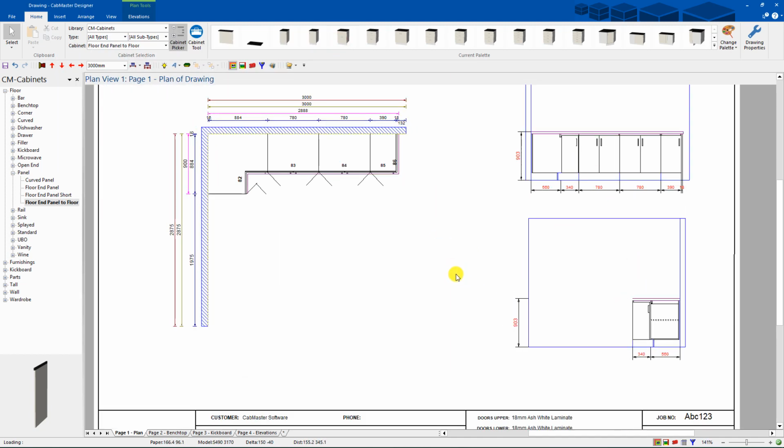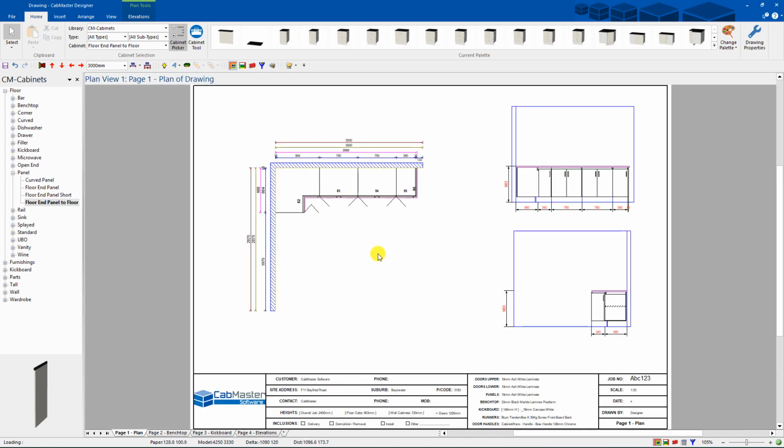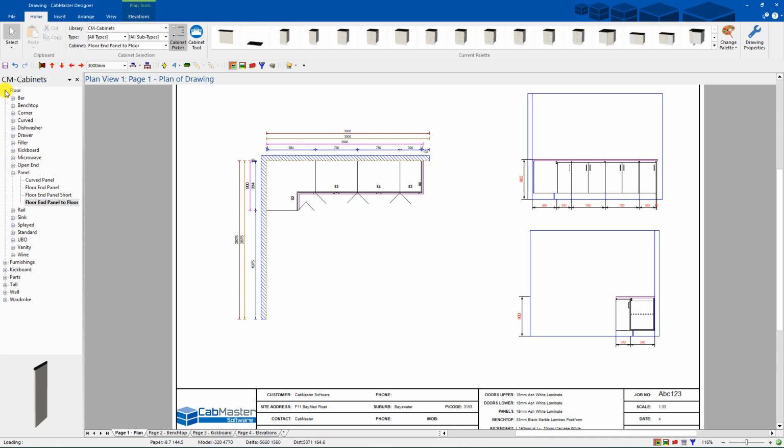So you can see what I've done on there. So that's quite happily done as well now. So we can keep drawing. I'm just going to throw some overheads in to show you what happens. So I'm going to grab a filler to begin with. Wall filler, 30mm. Again, push against the wall you want to go on, then slide it into the corner. You can see it's now appeared here and here.